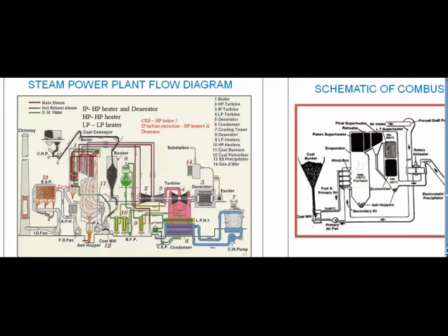25 mm size. This crushed coal through conveyor belt is transported to the coal bunker, which is located above coal pulverizer. From bunker, a regulated flow of coal is fed by gravity to the pulverizers, which is then ground into fine powder of 75 micrometer particle size.